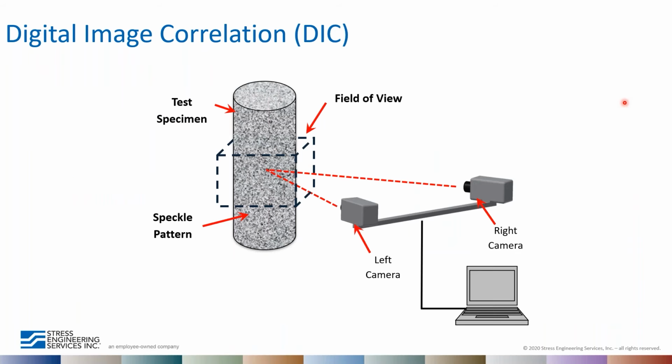And so there is a somewhat new system that addresses all these issues, and that's called digital image correlation. The way DIC works is you have a test specimen that you paint with a black and white stochastic, which means random, speckle pattern of black and white dots. And you have two cameras in stereo that film an area of interest, much like your eyeballs, that can pick up three-dimensional movements.